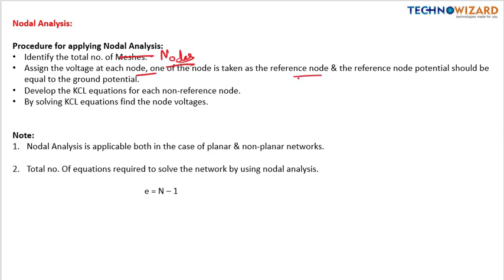One of the nodes is taken as the reference node, and the reference node potential should be equal to the ground potential. Now develop the KCL equation for each non-reference node, and solve the KCL equations to find the nodal voltages. Notice it is applicable for both planar and non-planar networks.